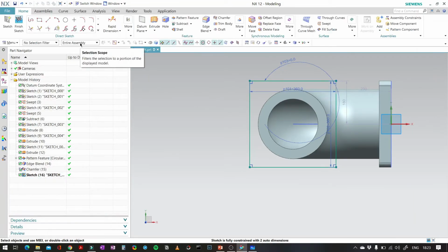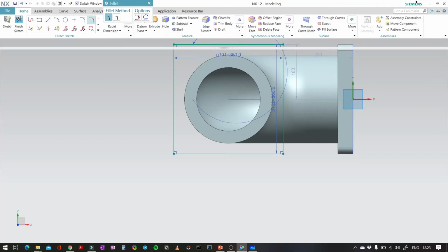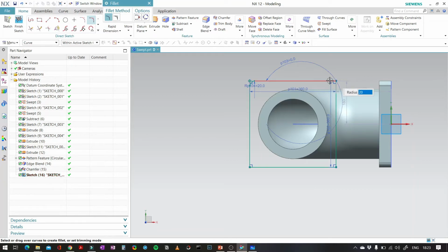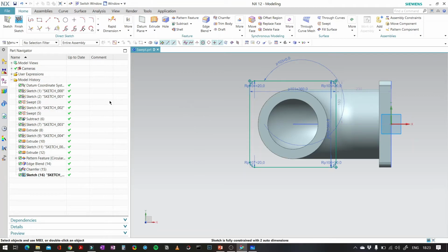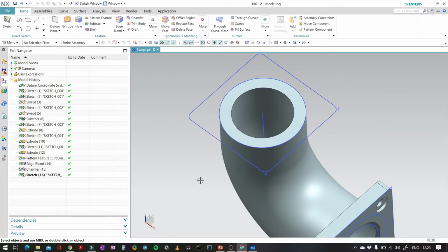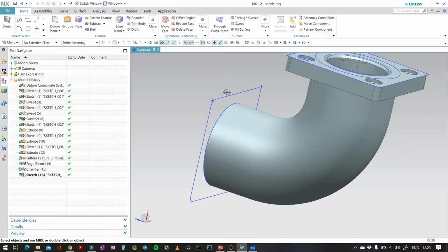Sorry, got into full view. Something is not going right today. So we'll have 20 mm again and again. Yeah, 20 mm of fillet over here, over here, over here, and over here. And this time I'll select this curve as well. Yeah, project that curve. So this time there is no need to sweep it to give the fillets after the extrusion. It is already there.